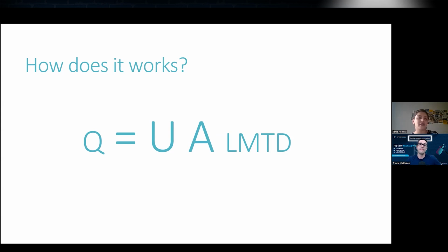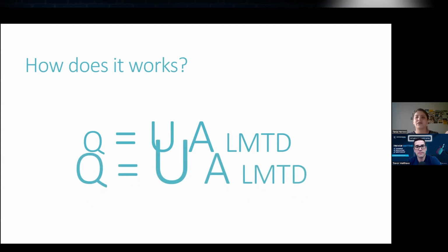So there are not many options, but there are some options that you can take. For instance, I know that in refrigeration, what we do is increase the refrigerant temperature, which means that we increase the discharge pressure and temperature in the compressor, right? In order to balance the decrease of the LMTD. But there are also other options, like increasing the overall heat transfer coefficient. I'm going to tell you how you can do that in the next slides, or what the implications of doing that are. So, point by point.